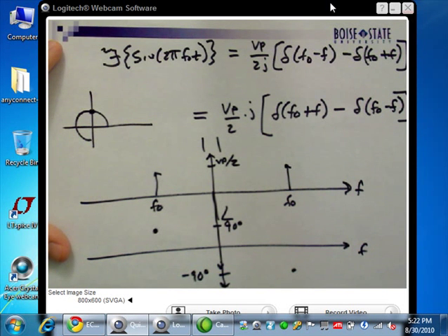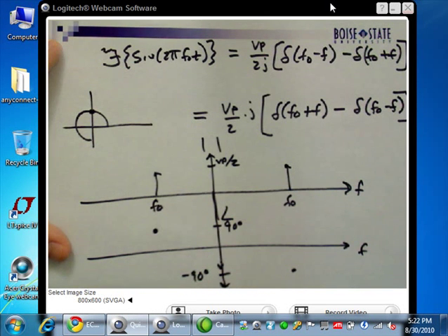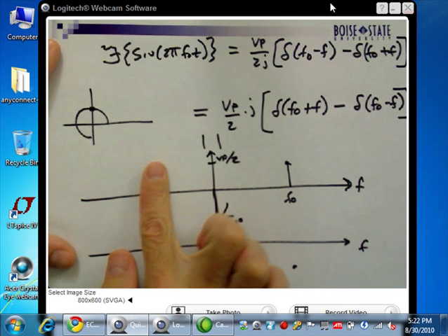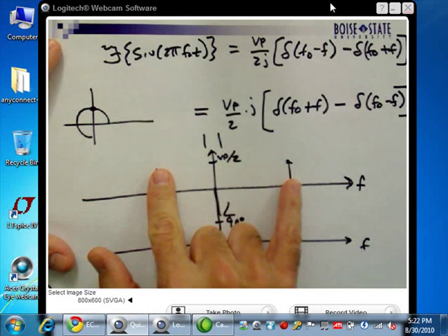Okay, so now if I go combine these and draw the signal as a single-sided waveform, okay, power has to be conserved. If I sketch and draw these over, I fold this one over onto here, the magnitude of the one-sided spectrum becomes VP. The power in each spectrum is conserved.